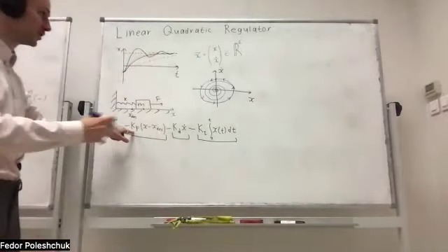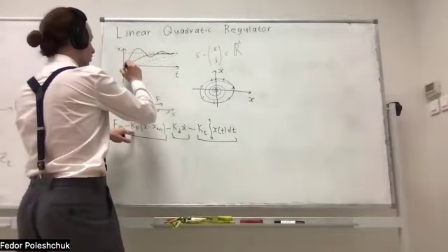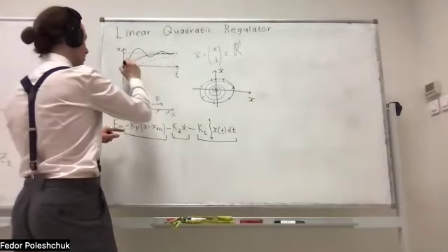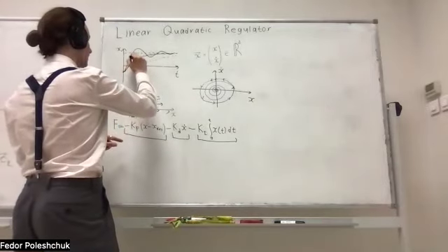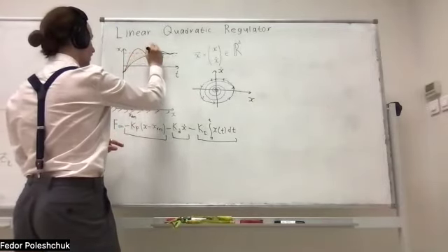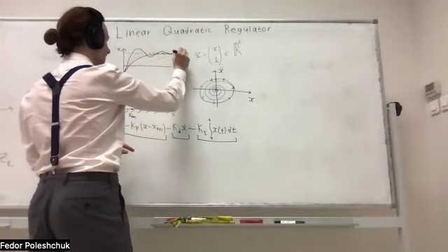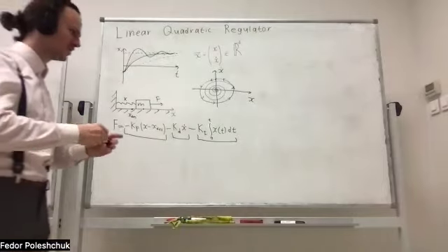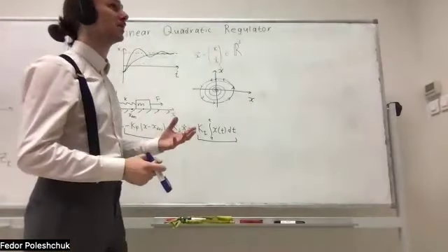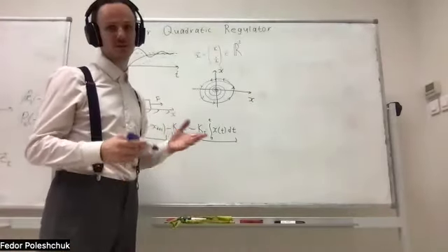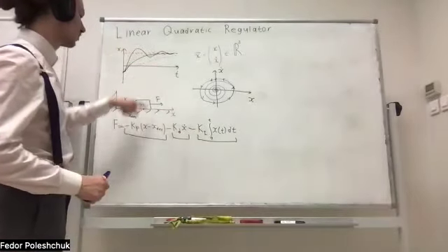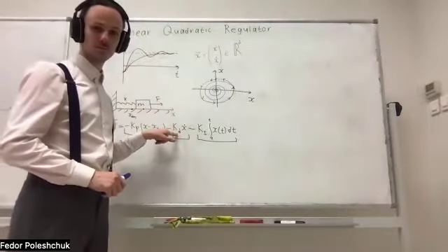However, if we overdo that, we can overshoot. It will basically mean that we are going too fast, and we are running beyond the desired position. And it could be dangerous if we, say, want to save the motors or something like that. So we can work with the overshoot with the D coefficient.